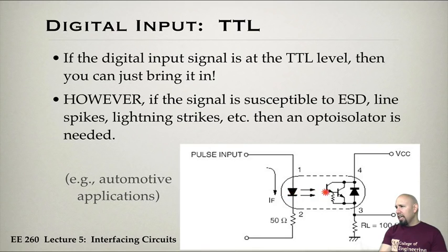So the LED is connected to what's called a photo receiver, okay? And that will pick up voltage, and the output voltage will basically be the same as the pulse. But if this goes too large, it'll still turn on the LED, but this side of the circuit, which is where your Arduino is connected, is not physically connected. It's connected optically. So the light here is what communicates this pulse or this digital signal to this output.